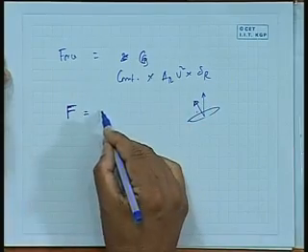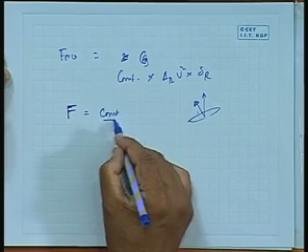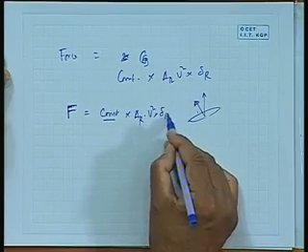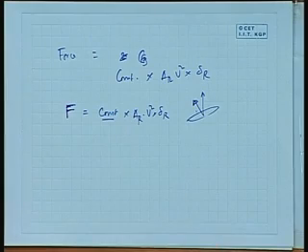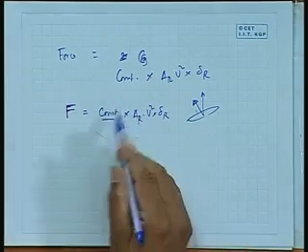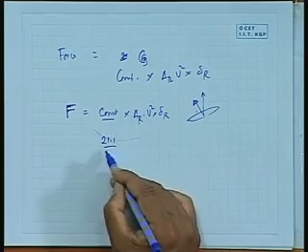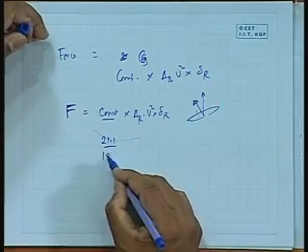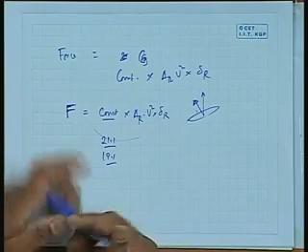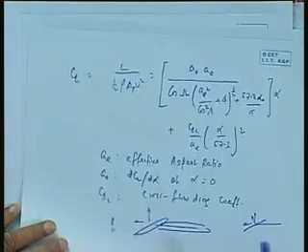It was estimated to be some kind of constant, that is the coefficient into area of the rudder into V square into an angle delta R. Like that it was doing. In fact, if you see that, this will turn out to be the same thing as CD, and this constant was suggested to be something like 21.1. People have given various suggestions, 19.1. From that onwards, people have actually improved, and this formula is an improved formula.